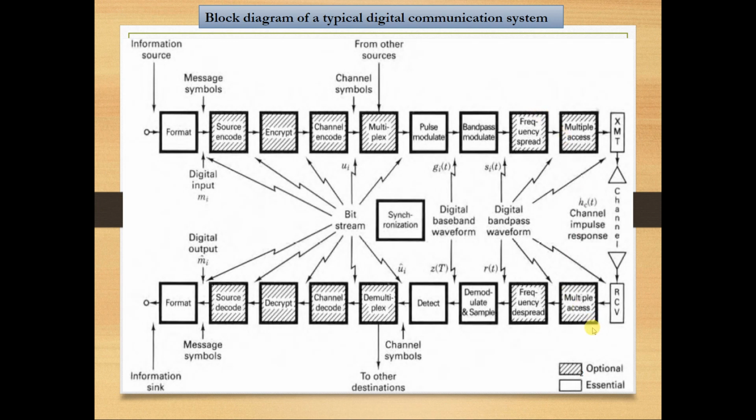And therefore, at the receiver side, you multiply by the same sequence that's used at the transmitter. Since now you have passed the channel, and your signal is in the receiver device, no longer in the channel, you are not afraid of interference now, so you multiply it by a sequence that allows you to return the signal back to its narrowband domain, not the wideband domain, which is spread below the noise level.